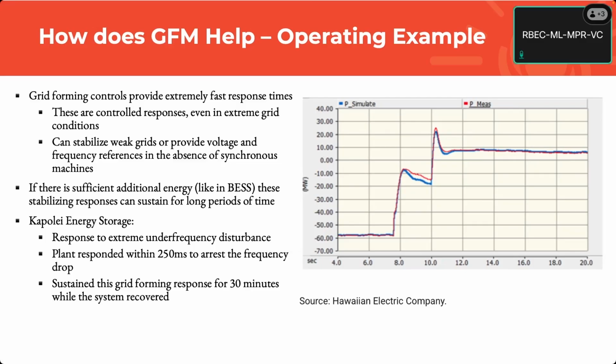That means the synchronous machine provides, as soon as you change that system quantity, an instantaneous difference between the internal and the external quantities. That means there's an immediate change in active and reactive power flow across that impedance. And that means very, very fast, right? Fast meaning immediate. It's a physical response, but uncontrolled. You're not controlling that. It's just happening because of physics.